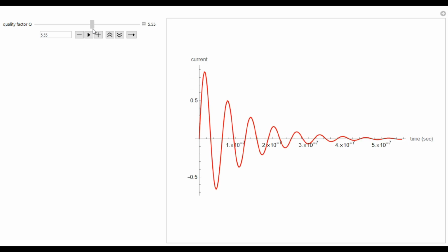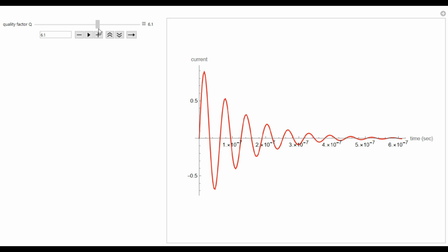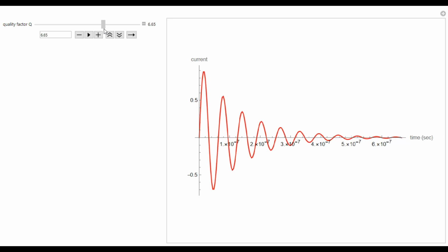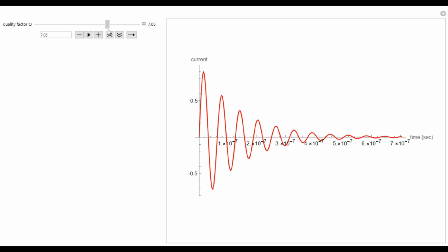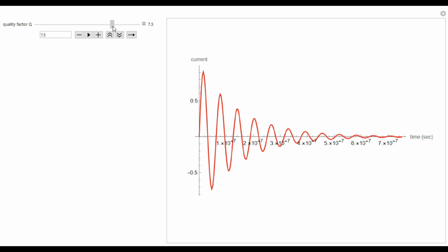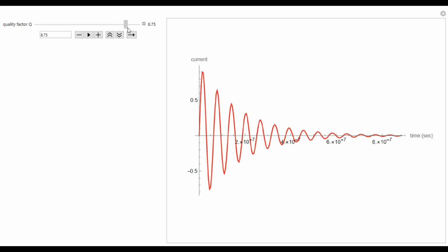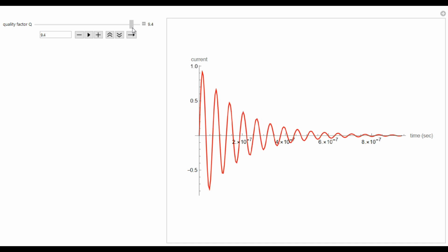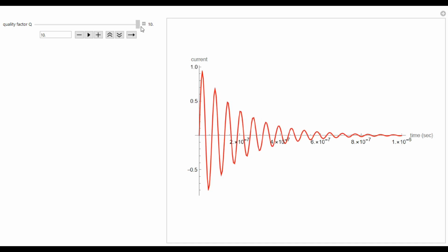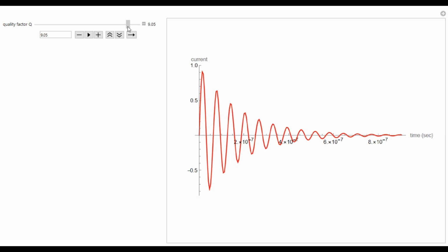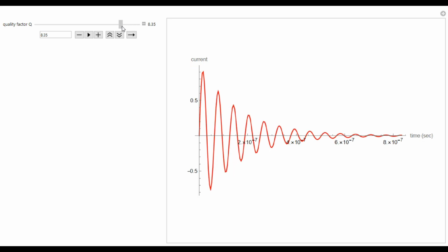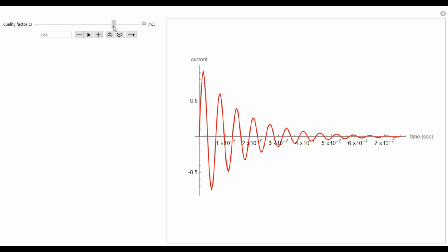A low Q factor leads to overdamping, a Q factor of 1/2 leads to critical damping, and a high Q factor leads to underdamping. Chapter 7. Applications of RLC circuits. RLC circuits are used in a wide range of applications, and their behavior depends heavily on the Q factor. 1. Radio tuners. Underdamped RLC circuits are used to select specific frequencies in radios and TVs.